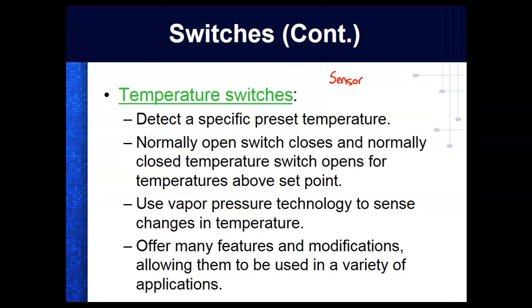The sensors that we use have two presets, an upper and a lower. Normally these sensors, especially electronic sensors, have what we call a deadband or a span, because if they didn't, they would constantly cycle. If you ever watch the temperature on your air conditioner, when it gets up to 70 degrees and drops down to 70 point something, it doesn't turn back on. It's got a span. It's got to drop down probably 1 degree before it turns back on.